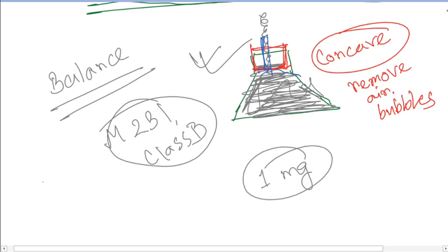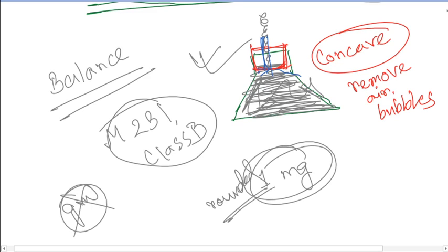In case of aggregates we said rounded to a gram, but not in this case. Here we are more sensitive about weighing, just because it is specific gravity, so we will round up to 1 milligram. This is our rounding specification for this experiment.